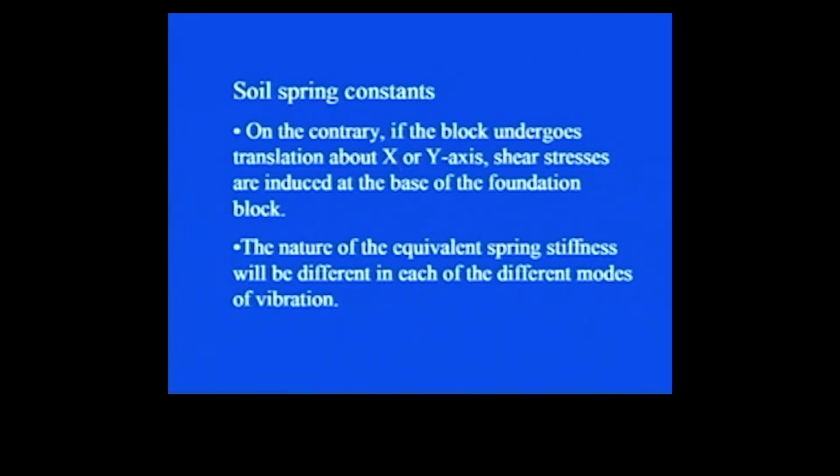So if, due to the dynamic load, this block undergoes translation, that is, the movement takes place along the x or y direction in the horizontal plane, then shear stresses will be induced, as compared to the compression which was there when it was subjected to the vertical load. Okay. So, two types of things are there.